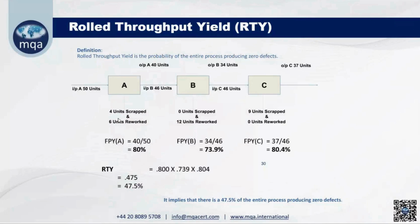So the machine is giving 10 parts rejected out of 50. So the first pass yield will be 40 parts divided by 50. 10 is minus from 50, so 40. So 80% is the yield of the first machine. Now we see here 46. Even after the rejection, we see 46 pieces we reworked. So these 6 pieces got added.